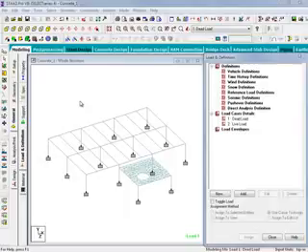Before I populate each load case with the load items that would be applicable to it, I'm going to first investigate what my input units are. And for this model, currently I'm set to kips and inches. Now I will eventually be applying a uniform member force to some of the beams in this model, and I'd rather enter this information in kips and feet instead of kips and inches. So at this point, before I create my load items, I'm going to change my input units.